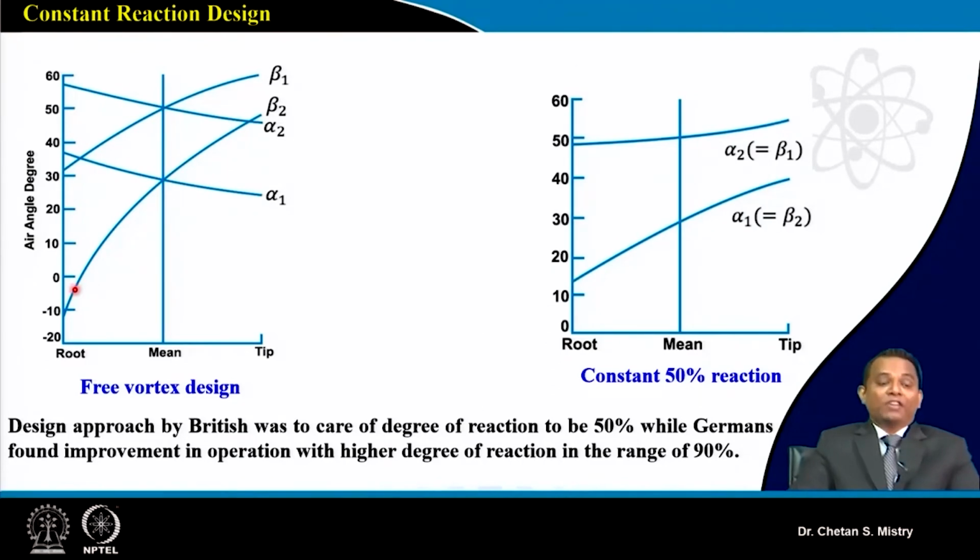Okay, so when we have this kind of design configuration, yes, this is a major challenge. So do not get confused with a highly twisted blade. You will say with present availability of machining, it is possible to fabricate this kind of blades. Yes, but when I have a highly twisted blade, my flow three-dimensionality will be very large.